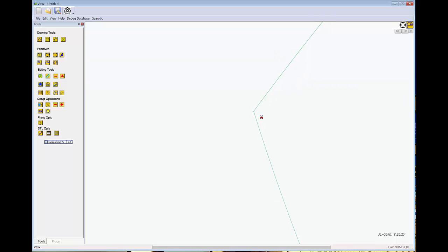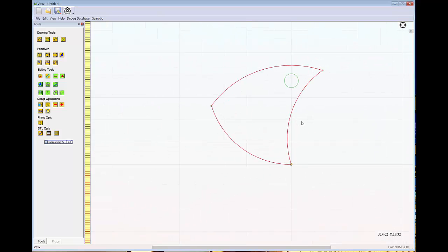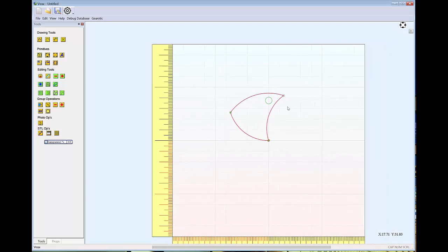And now I'll hit Escape to get out of my scissor tool, and when I select contour, we can see that the start doesn't quite hit the end. So I'm going to lift up the end and move it to the start. That is a move of probably 1/10 of a millimeter, so it's not significant, and it's a good way to close a contour which is not closing for you. So here we have our first vane.